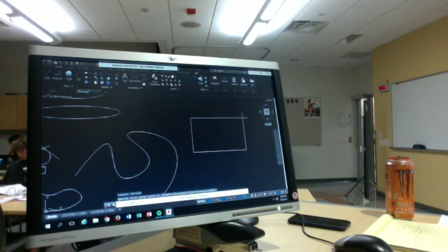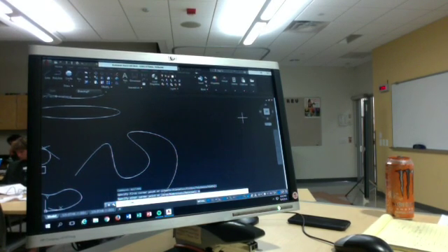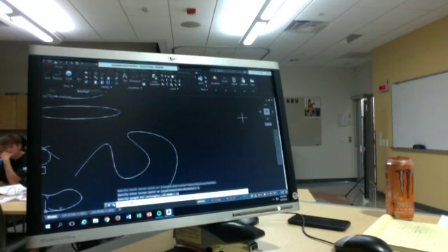So if you want to do dimensions, you type in D. Now the important thing to realize here is that first you want to specify your length, and then you'll specify your height. So this one's going to be, let's say, 22 long, and then height. It does say width, but that's because when you're looking at your XY, imagine you're looking down at the floor.